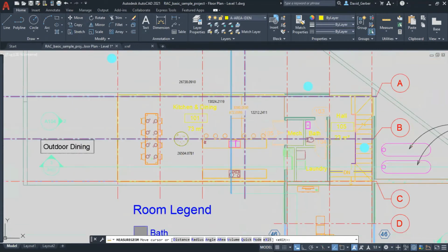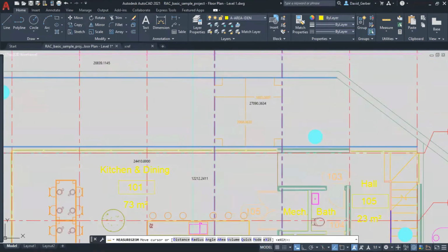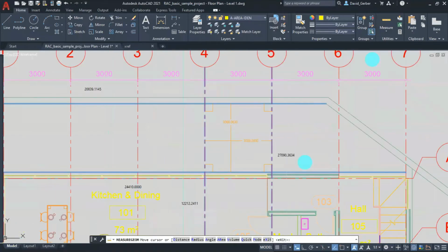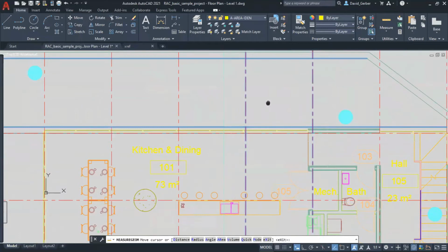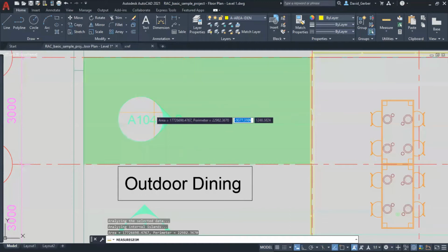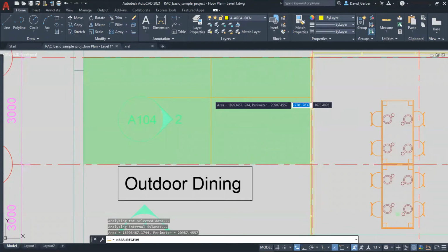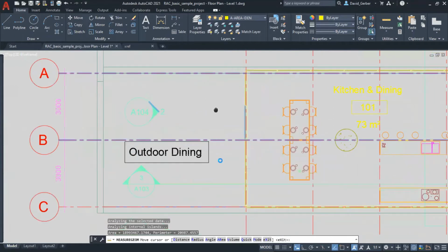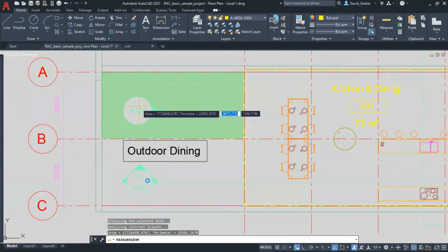There's a lot going on in this drawing, but you get the point. You can see these little squares here, which mean that's a 90-degree angle, so it's helping you there as well. If we click on it and hold, you'll see the area start to come up. If I hold shift, and it's not picking this little area up, and I click again, it'll give me that whole area. It's in millimeters squared, so 18.9 meters, but we can quickly get the areas of certain regions without having to use the area command.